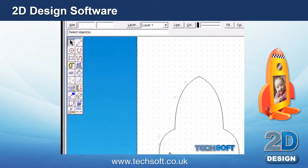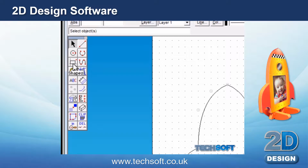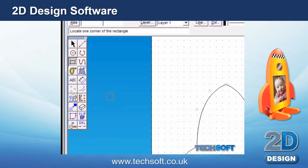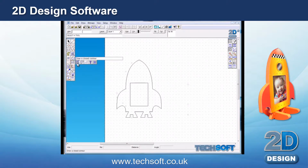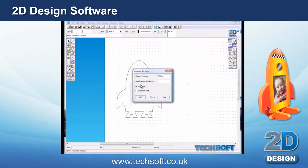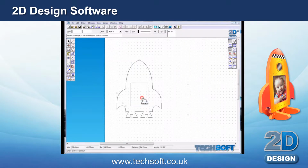Next we'll want a window in this photo frame just so you can see the picture. So we go to the rectangle. Using the absolute coordinates, you'll be able to accurately draw this window in the centre. Start drawing it. And then in the same windows, you'll notice that I'm doing this by 30mm by 40mm. Next, I'm just doing the contour lines. This 2.5, and this is just going to draw a line on the outside of that rectangle we've already got.